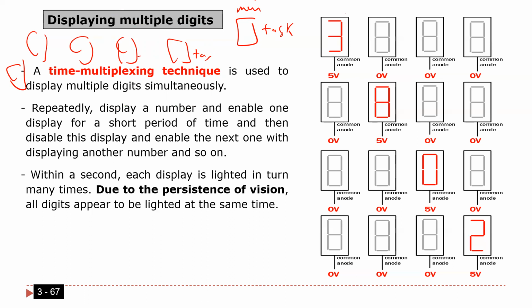which for sure is not true. As I explained before, you leave the main, go execute something, so you suspend this task, then come back. But if you do it very quickly, you are going to feel like this is multitasking. This is very important, because if you just use the main, you cannot make big applications. If you want to create a big system, the system has to do many things. That is why we use interrupts.